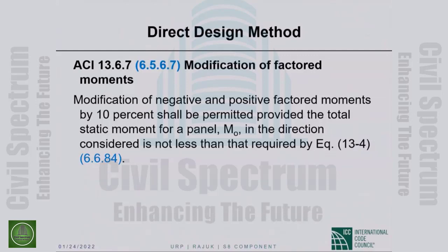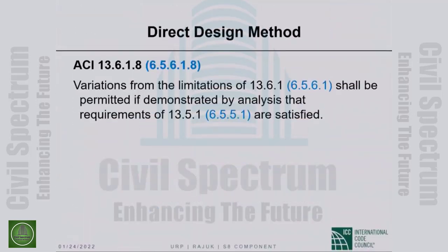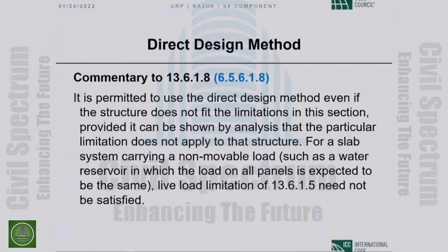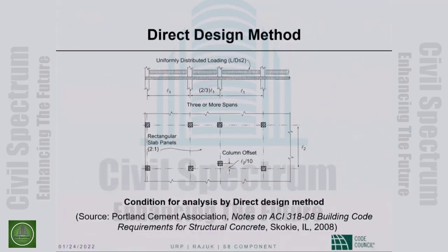Modification of negative and positive factored moments by 10% shall be permitted, provided the total static moment is preserved. You cannot violate statics. Now, variations from the limitations shall be permitted if demonstrated by analysis. Those things, I don't know how important. This also I will let you read.